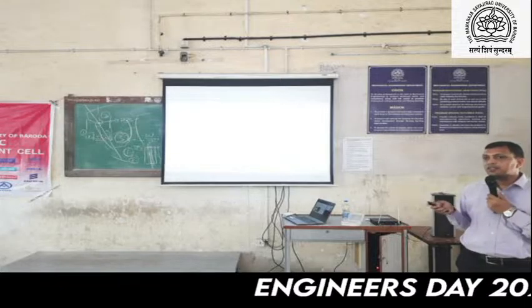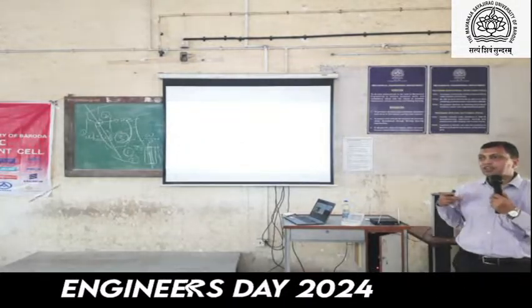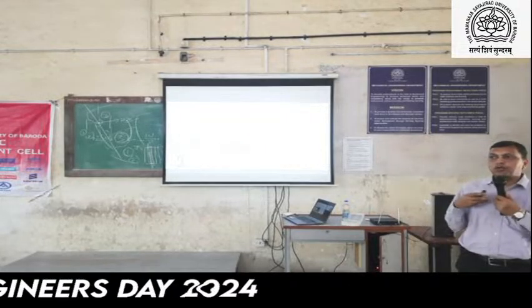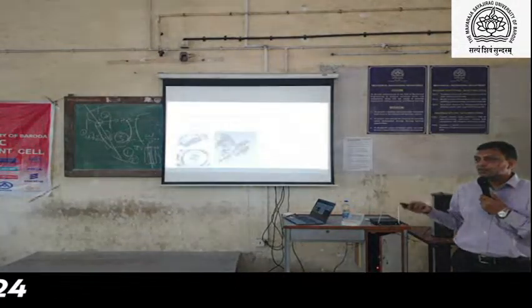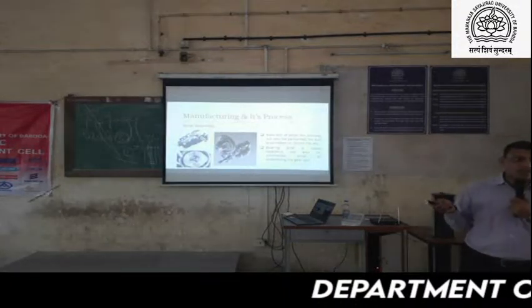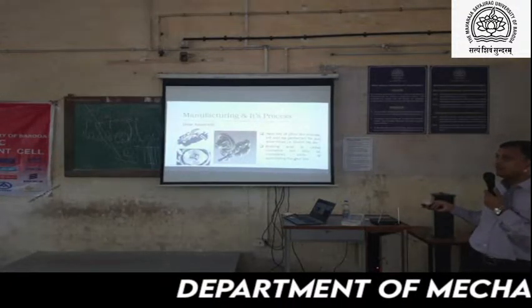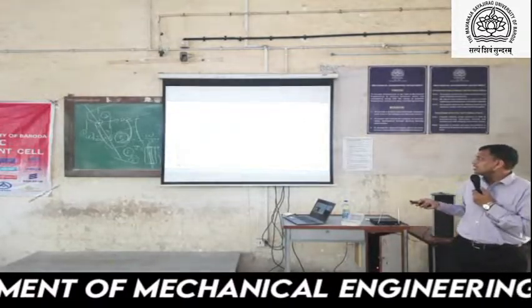But in taper roller, two parts are fitted at the time of assembly. If we preload that, it will generate a temperature issue, so that should be controlled during assembly. So the axial plane is what we have to maintain during assembly.